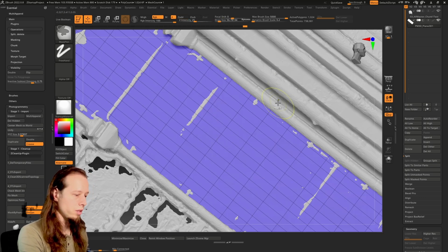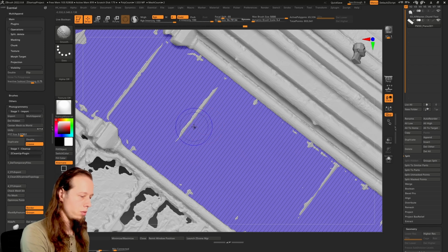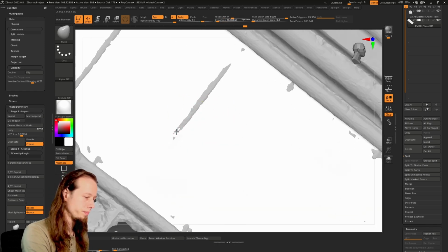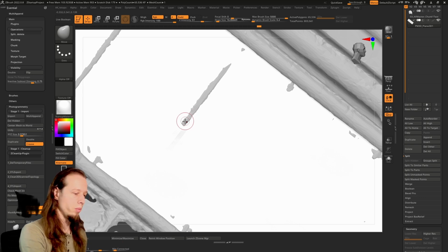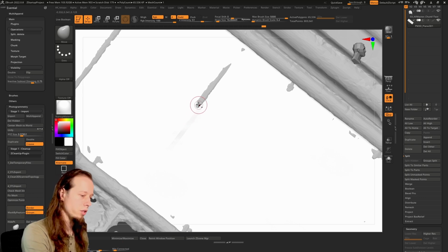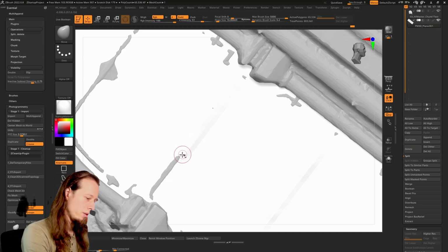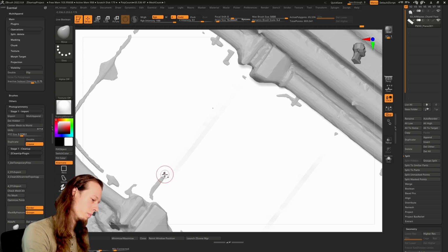We should actually increase the resolution of that panel to make those changes as local as possible, because again we're gonna make a projection of the texture, so any difference between our model imported to RealityCapture and the source data is gonna appear as a blurred texture, which is not ideal.